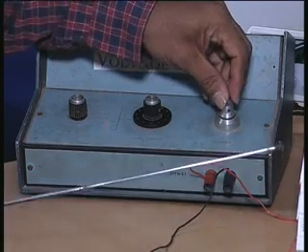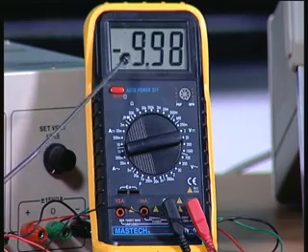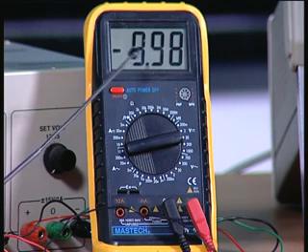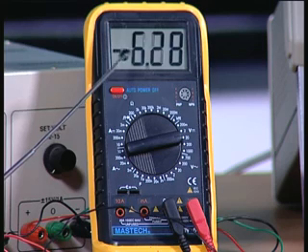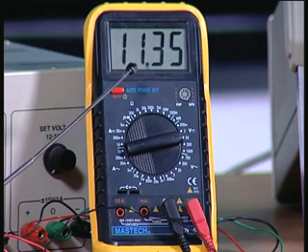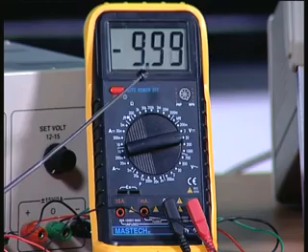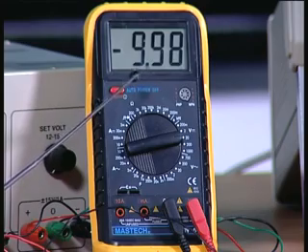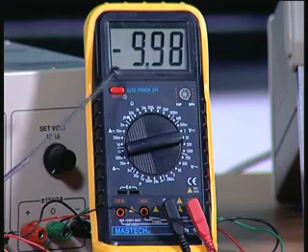So now I would like you to watch the multimeter as I keep increasing it. You find when I just move by a very small extent, it has come to minus VCC. I again go back, you will find it comes to plus VCC again. I go back again, you would find it becomes minus VCC. So it is at this threshold that this happens, and if you measure this, it will be very close to 1.2 volts, or whatever is the input at the positive input, that is at the non-inverting terminal.